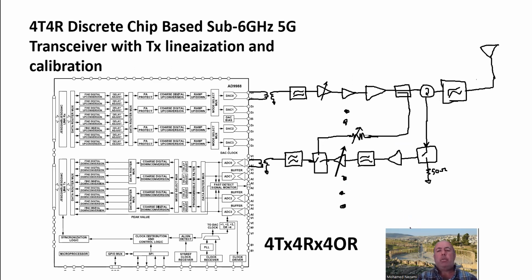Also, since the signal level is strong in here, we decide on how much coupling we need in here, and this is high power, this is a PA. So we could also multiplex the use of one of the MIMO receivers themselves as a way to do linearization, since linearizing that PA doesn't have to be always on.